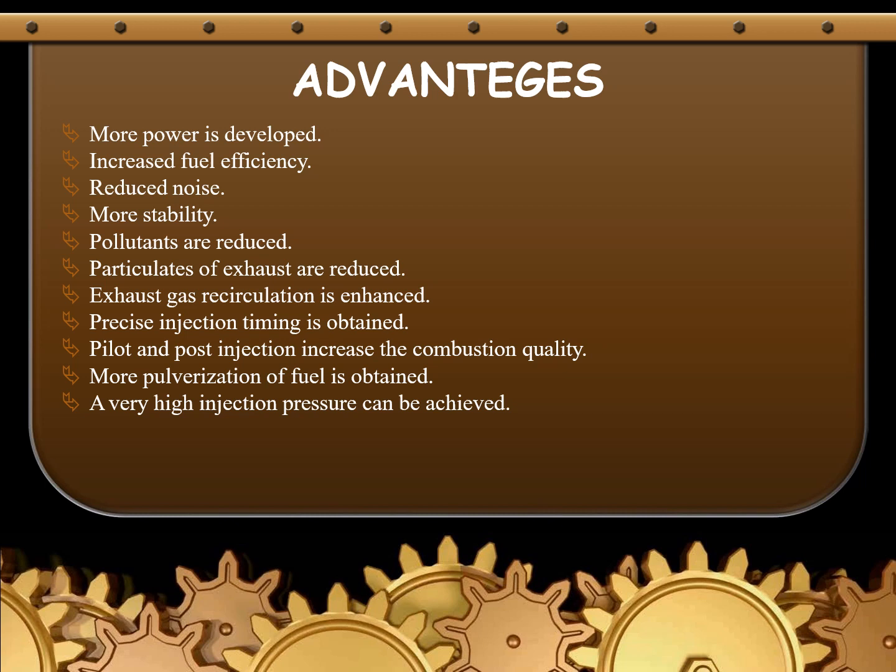What are the advantages? More power is developed, fuel efficiency increases, noise is reduced, there is more stability, pollutants are reduced, exhaust particulates are reduced, and exhaust gas recirculation is enhanced. Precise injection timing is obtained. Pilot and post injection increase the combustion quality. More pulverization of the fuel is obtained, which means the air and fuel are mixed thoroughly, and very high injection pressures can be achieved.